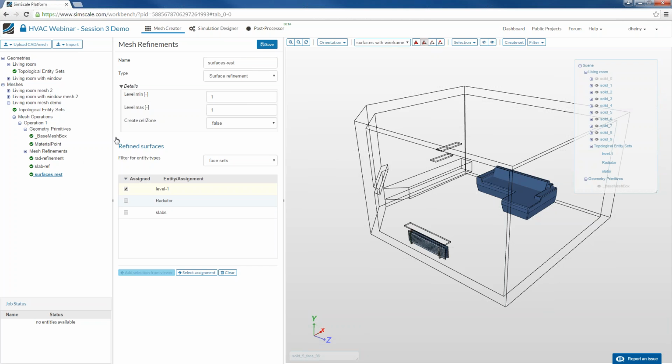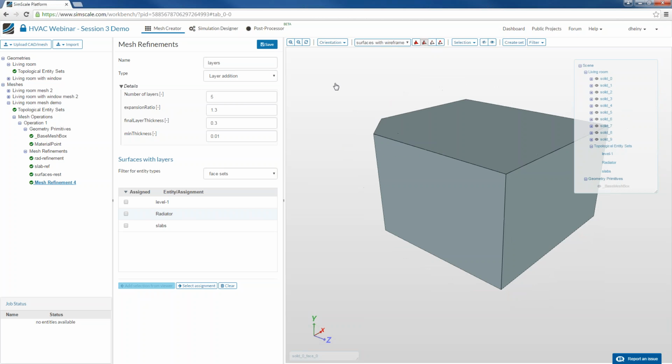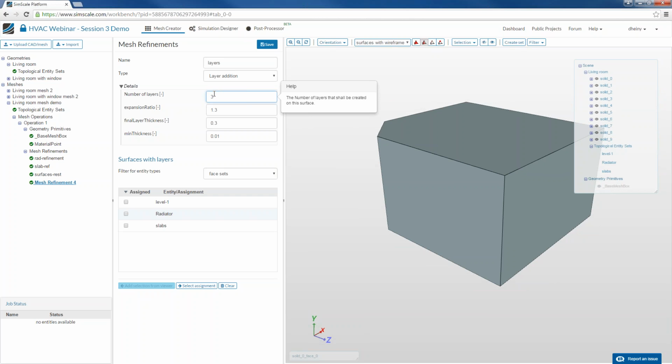As a last step, and then we're set with mesh generation, we're going to generate layers. These layers mean that close to all walls, we expect a turbulent boundary layer, or at least some sort of boundary layer, because close to the wall we're going to see no movement because the air molecules stick to the wall. But a little bit away from the wall, we're going to see all sorts of convective heat transport and velocity effects. And so between this velocity and the zero velocity directly at the wall, we will have a higher velocity gradient.